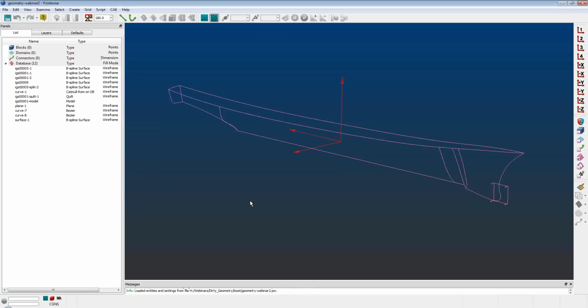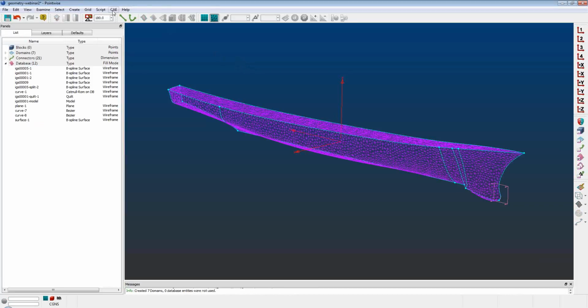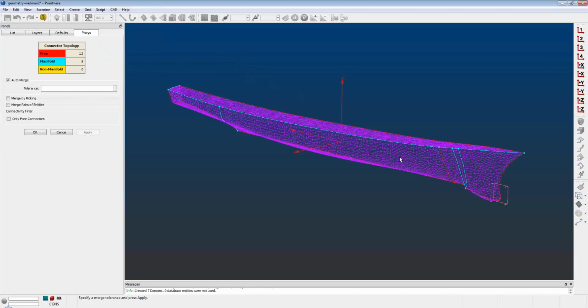To demonstrate the fault-tolerant meshing method, Travis first creates meshes on all the surfaces, and then he's going to use a tool to check if the internal grid curves are shared by more than one surface. Like I discussed in the schematics, when the internal curves are blue, two surface meshes share their grid curve, and this is what we want. And we see this where Travis has his mouse right now.